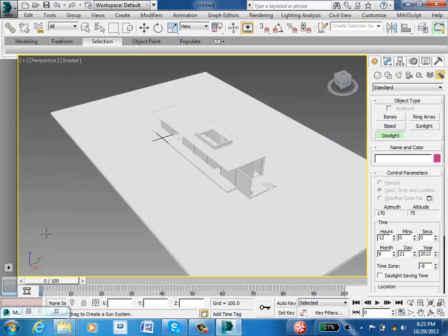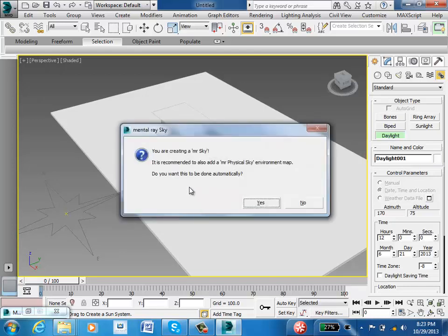And what I'm going to do now is I'll do it over here so you can hopefully see it. I'm going to left click and hold. And as you can see there, a compass starts to show up. You guys can see that, right? So basically, this is the system that you're tying the light to. I'm going to release, and north is your Y direction, east is your X direction. So when you're building your Rhino model, you can kind of do that. We can also rotate it in here, and I'll show you how to do that.